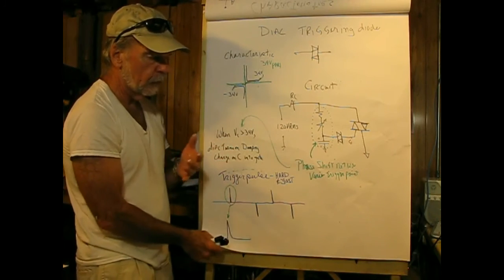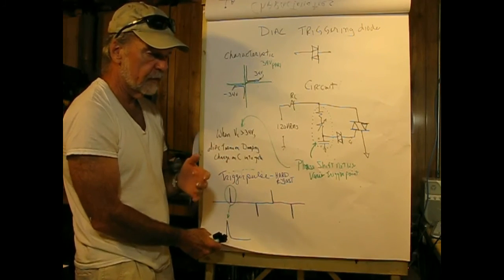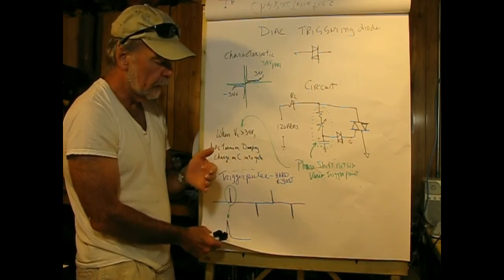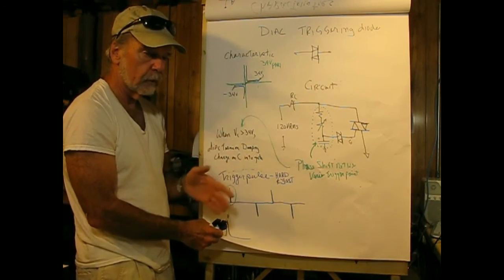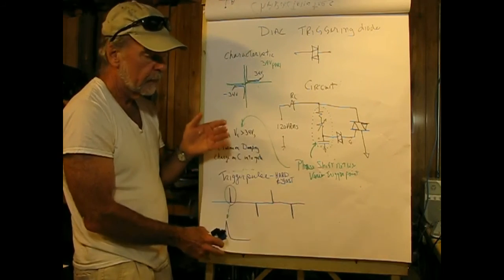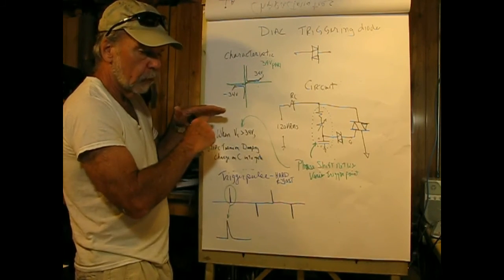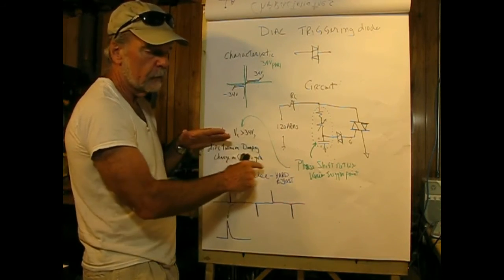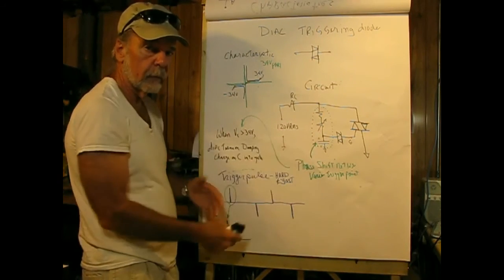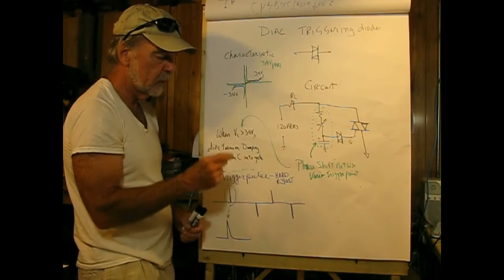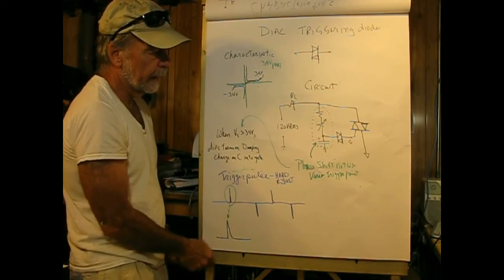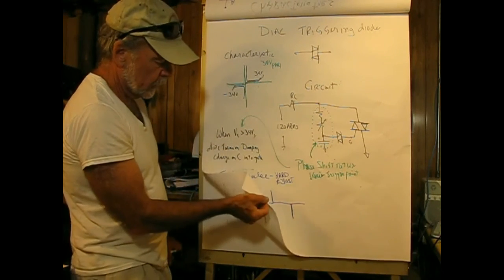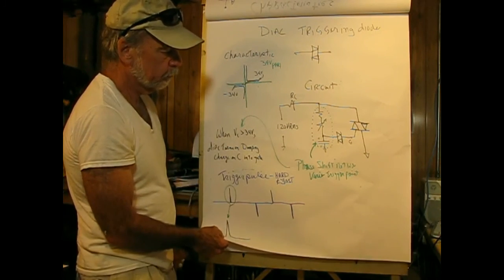We don't want to get into those positions like we had with MOSFETs, where a slow rise and fall time on the gate produced a large amount of power as the drain voltage lazily moved down towards zero and the drain current lazily moved up to its limit from RL. We want it to be quick. So that's what a trigger diode is for, and there are several different members of the family which do the same thing.